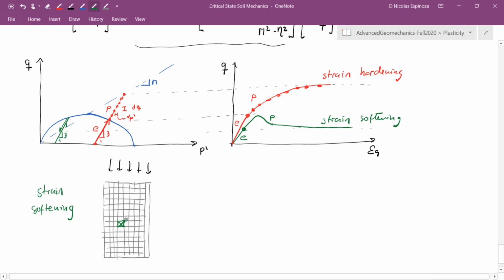And what's going to happen? The stress that this grid block was taking right here now is going to be taken by the adjacent blocks. And remembering also the theory of shear strength, we have seen that fractures will tend to align onto a given angle, right? So very likely the material next to it with a higher stress could be either in this diagonal or in this other.